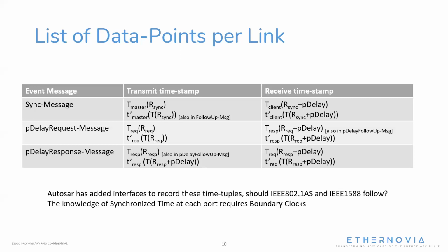Same thing for the pDelay response message, where we record again in local time when it was transmitted, and we associate again the time in synchronized time when it was transmitted on the responder.